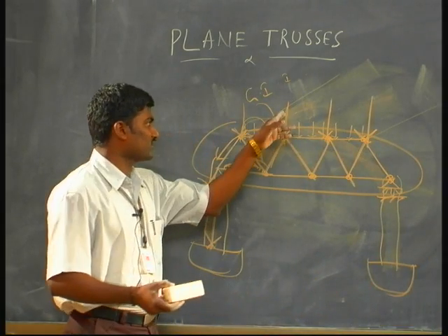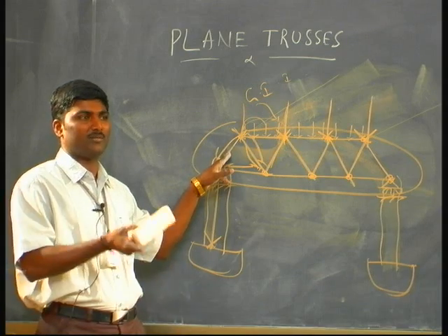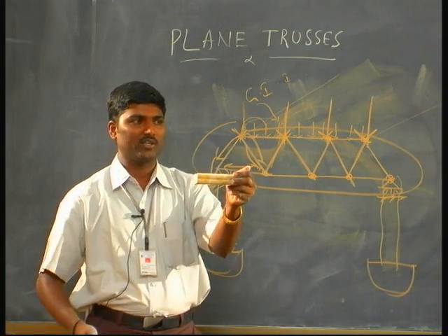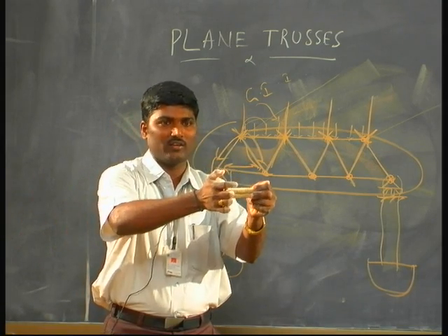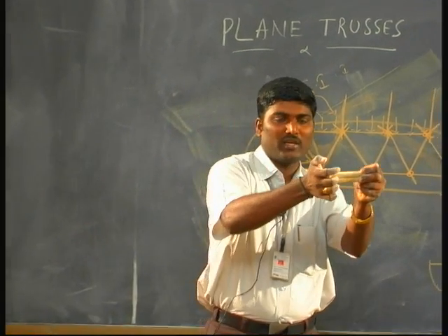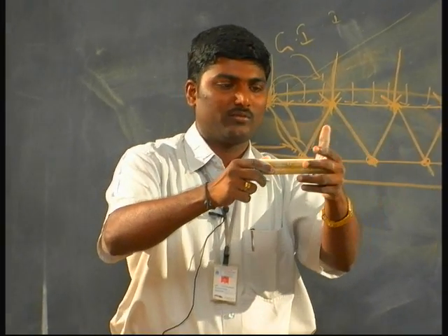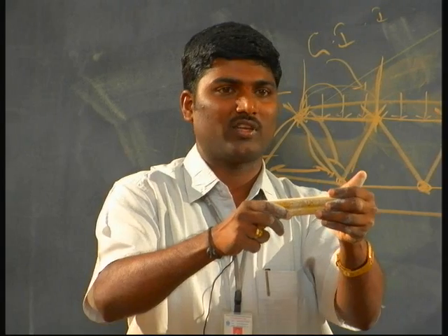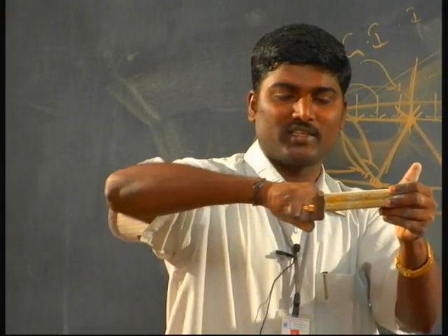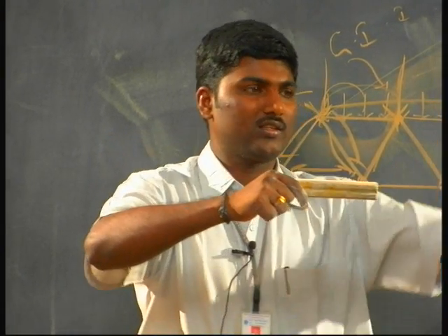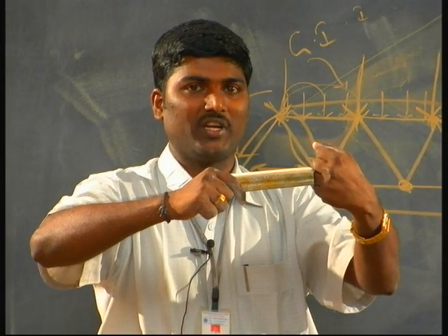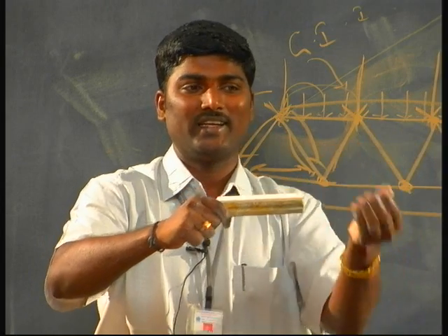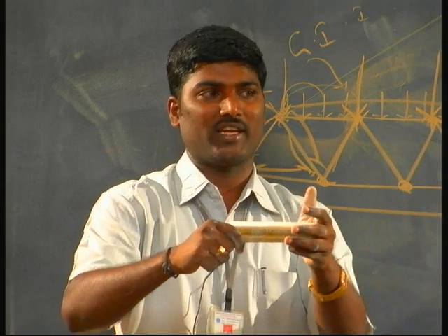So I said because of forces, forces will be developed in the member. Why? Say if I take a member, if I rigidly support here and apply a force here, the member is not moving. Why is it not moving? I am providing a support here. So if I apply say some 100 kg here, this is offering some 100 kg, that is why this is not moving. So this 100 developed is called support reaction.